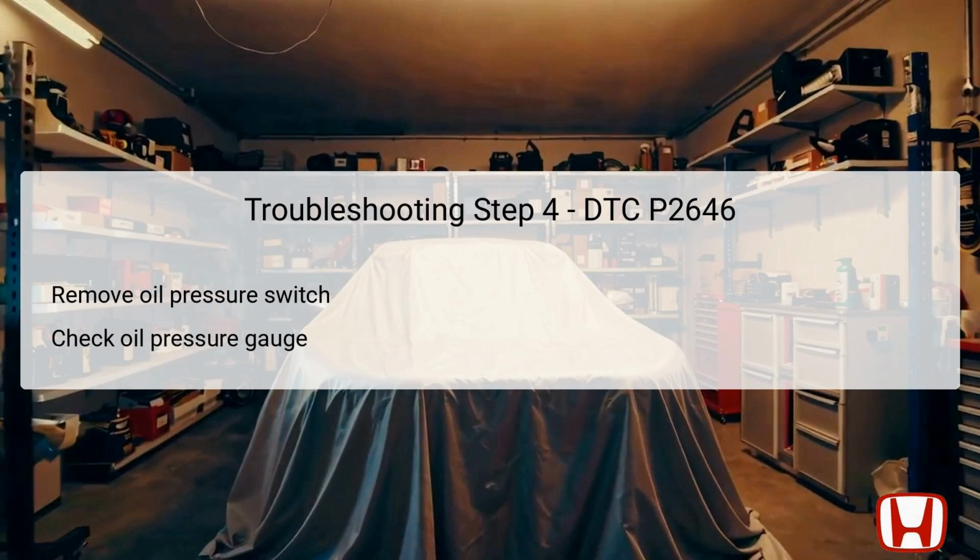Troubleshooting step 4 demands a more hands-on approach with components, starting by switching the vehicle to the off mode. The next critical action involves removing the rocker arm oil pressure switch from its mount. To correctly assess the oil pressure, special tools must be utilized.